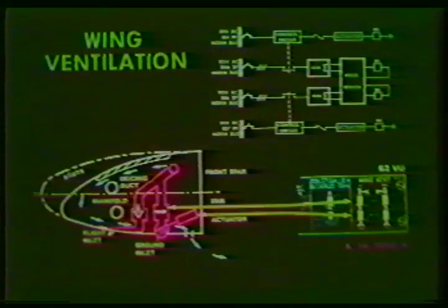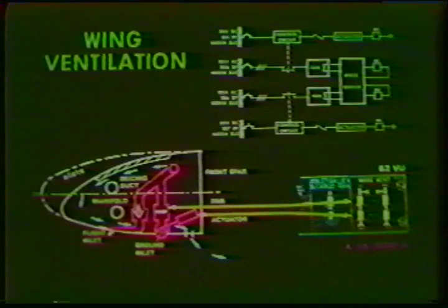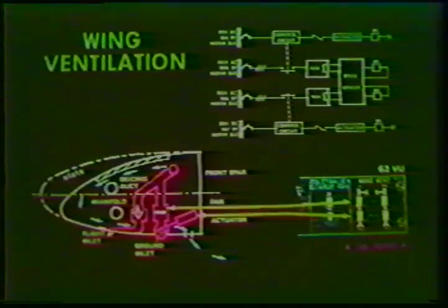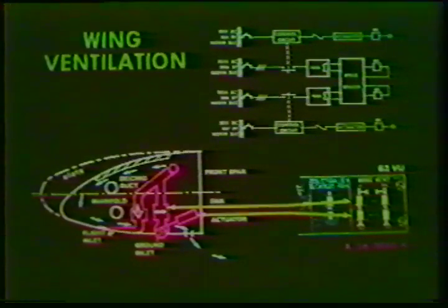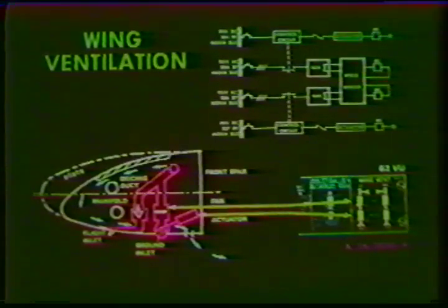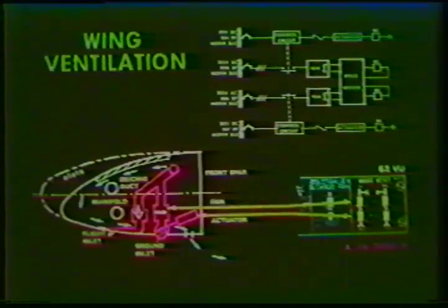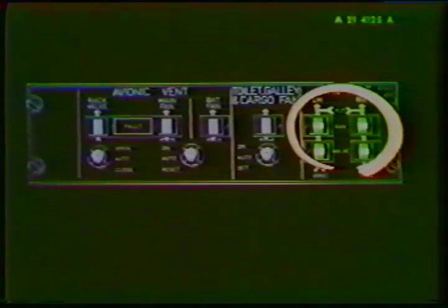The ram air intake is for flight operation. During ground operation, airflow is induced by a fan. The ground inlet is opened or closed with a flap driven by an actuator. The operation of the fan and actuator is controlled through the landing gear air-ground logic. Situations are indicated by magnetic indicators. This concludes the presentation of the A300 pneumatic system.